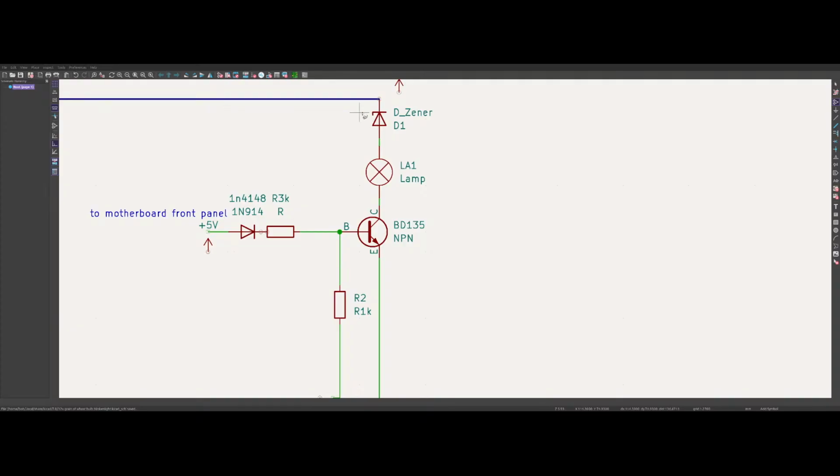It's a lot better if you have the light bulb at the collector. The light bulb is an unusual type of resistor. It draws a lot of current when it turns on, and then the resistance goes up as it warms up. Either way, it acts as a resistor, which prevents too much current going to the transistor.